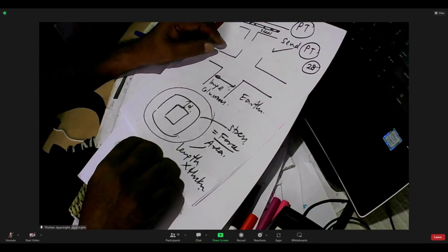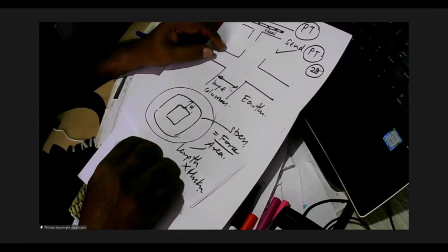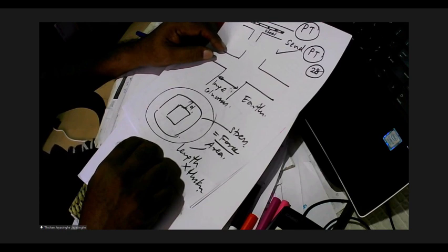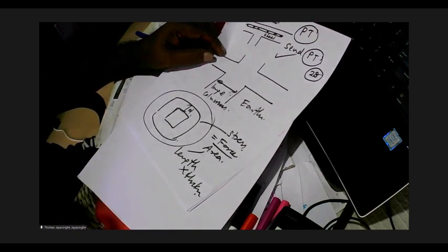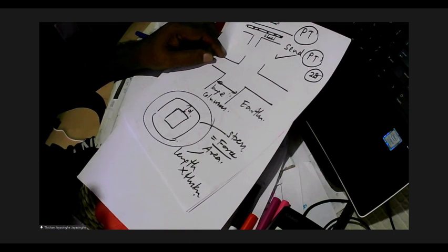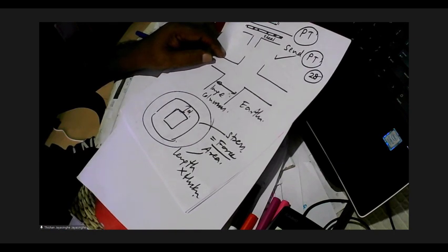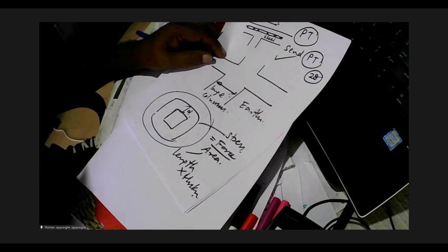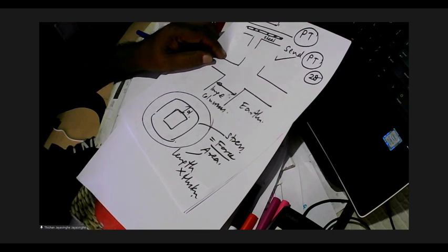And also regarding the assignment, I told you what to do. We have to design a continuous beam with the spreadsheet, and then find a tendon profile and show that all those stresses are okay. But only thing is, don't use the spans that are given in the spreadsheet. You can go for different spans, and also the sign convention in the spreadsheet I have given is different, but the answers are the same. So you can convert it to compression positive and tension positive. Okay, Bashita?